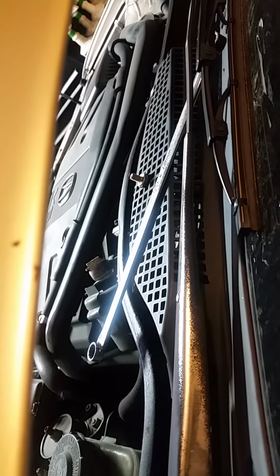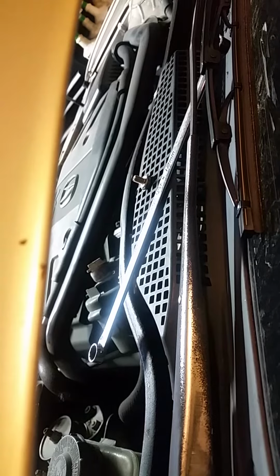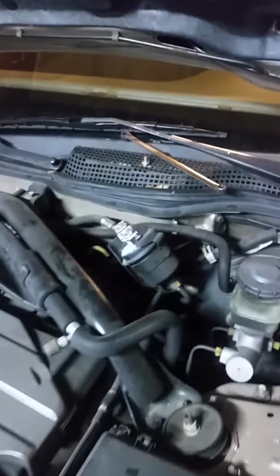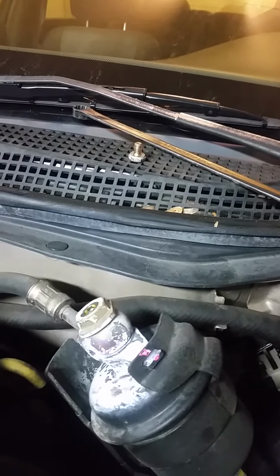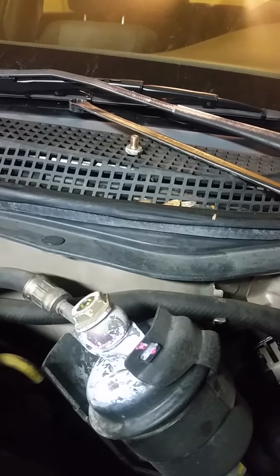It's open now. Okay, well, this was actually not advisable. I kind of had an inkling when no fuel even oozed out of what should have been somewhat pressurized fuel line. Basically, what's happening here is I have no fuel pressure.